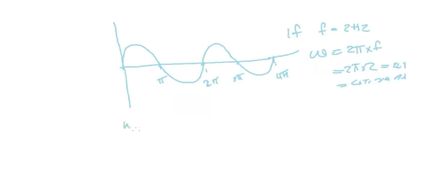Here omega t is on the x-axis. Omega t equal to what? Omega is equal to 4 pi, into 0 here, and here it will be 4 pi into, is it 0.5? No. The value is pi. To get pi, 4 pi should be multiplied by 1 by 4. That is 0.25 seconds, so t is equal to 1 by 4. The value will be here. And 4 pi into something should be 2 pi. What will be that? 1 by 2. At 1 by 2 second, the value of voltage will be here.